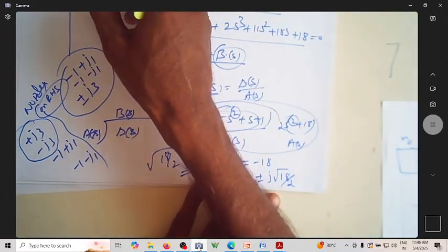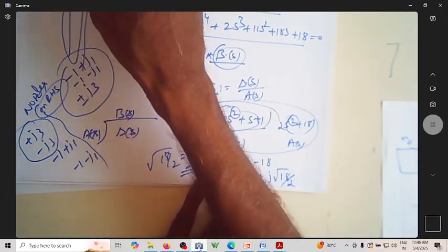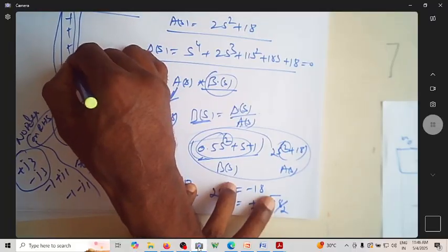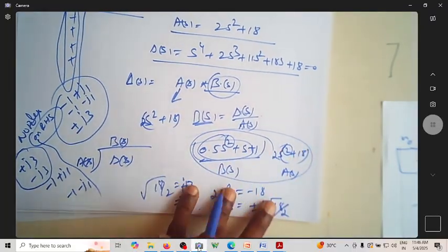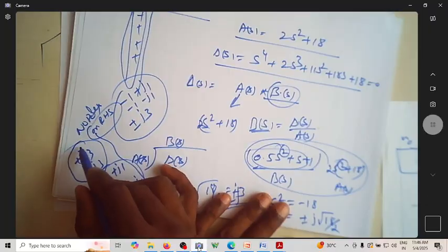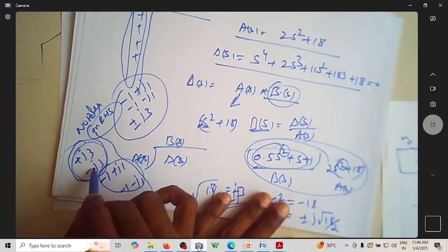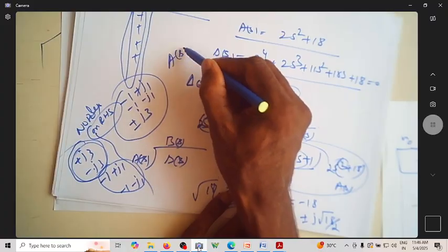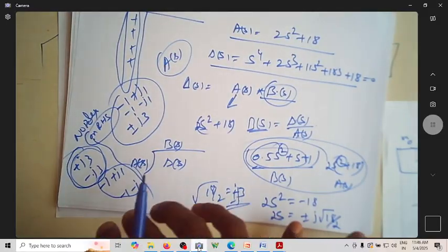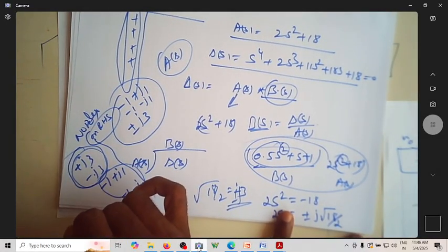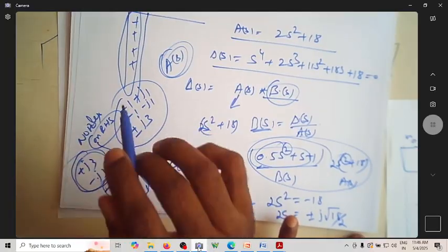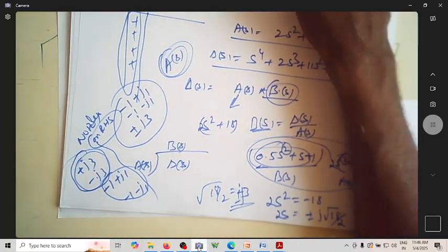So first, the Routh array tells us how many poles are on the right hand side of the plane. If there is no sign change, then no poles to the right hand side. How about the poles? As per this, 2 are on the left hand side and 2 are on the imaginary axis, because you ended with an auxiliary equation. An auxiliary equation may yield poles on the imaginary axis. Of course, auxiliary equation means you're going to have poles on the imaginary axis of the S-plane.